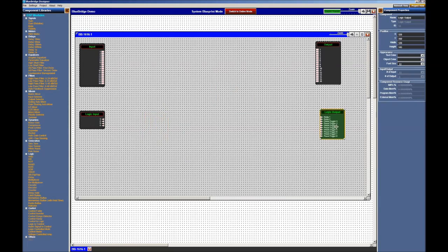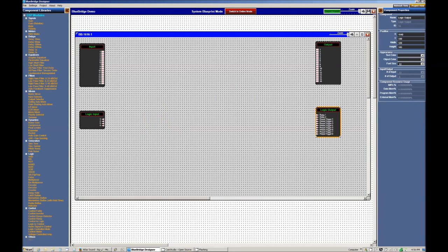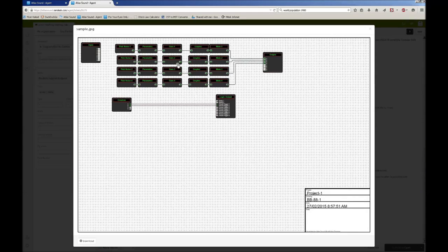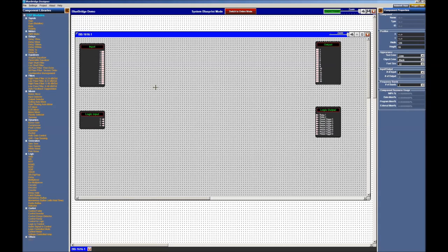This is what we care about making. So the first thing we had on this design is, like I said, 4 pink noise generators, 4 parametric EQs, 4 gains, 4 graphic EQs, 4 mutes, and these went to outputs. We had nothing on the inputs, and we had 2 preset triggers. So the first thing that I'll go ahead and do is drag in our pink noise generator from the left, and that brings us there.